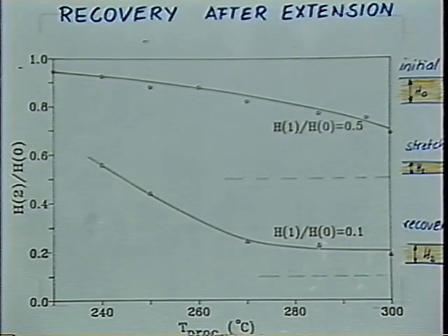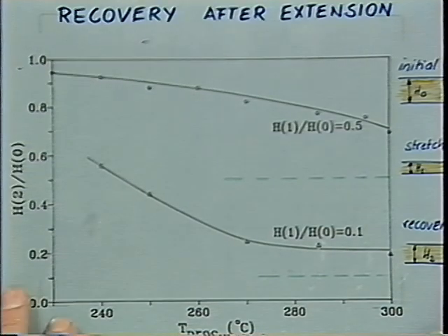The material is highly elastic, and this is an elasticity which comes out of the superstructure of this material. It's so-called Frank elasticity of the material. It's not the entropic elasticity which we would expect. And this type of elasticity would affect the fiber blowing behavior, film blowing behavior or blow molding behavior when you produce planar objects with liquid crystal material.